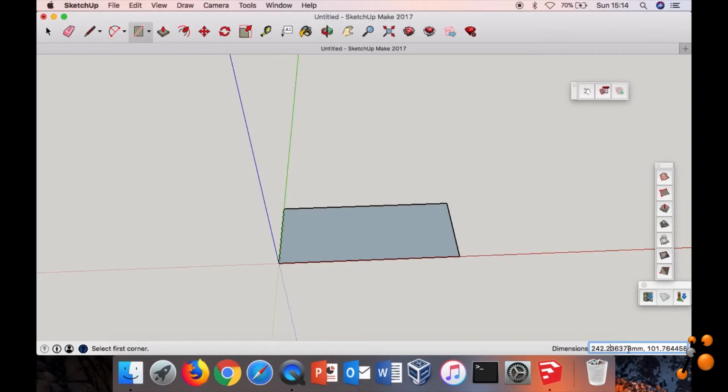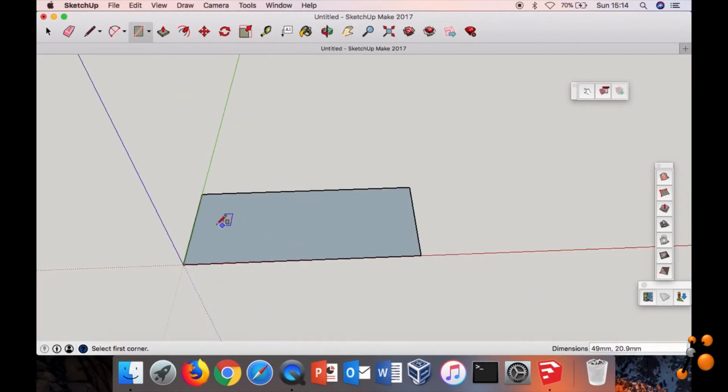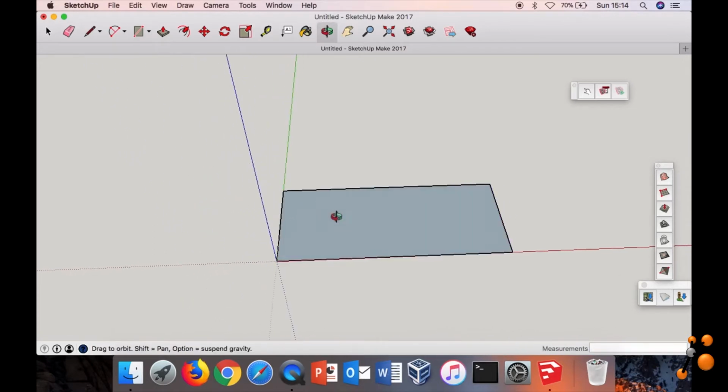It will be, so here let's put, to start, 49 millimeter, and here we know that the thickness of the wall will be 4 millimeter. Then we have the diameter of the lens, which is 12.7. We add 0.2 millimeter, so it will be 12.9 to be sure that we can insert the LEDs, and then again 4 millimeter. So 12.9 plus 4 plus 4, it's 20.9. Enter. Wow, it's small. Okay, so now we have this. Okay, let's move a little bit.